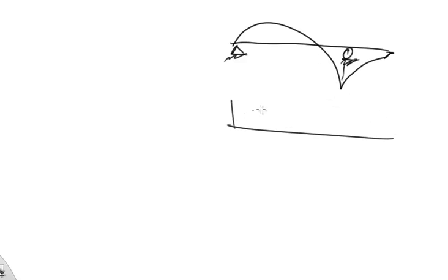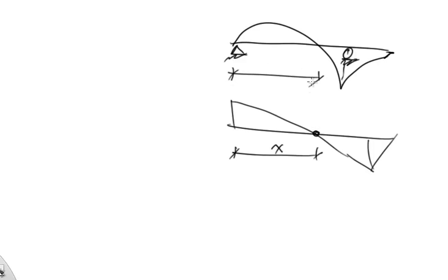and let's say I have a shear diagram that maybe looks something like this. I don't care, okay? But the question was, we know for sure that sometimes we need this x, the location of the zero shear, because that corresponds to the maximum moment. But why do we care about where the moment is zero on a beam? Well, that's the first part of his question. The second part is, is there an easy way or a quick way to find it?